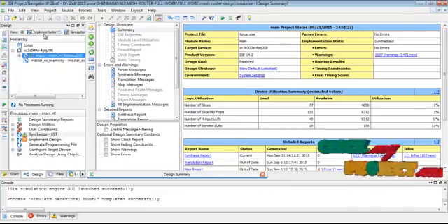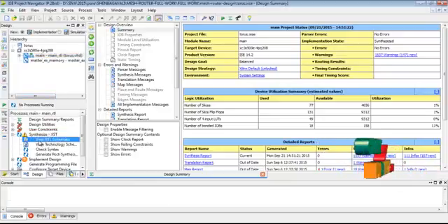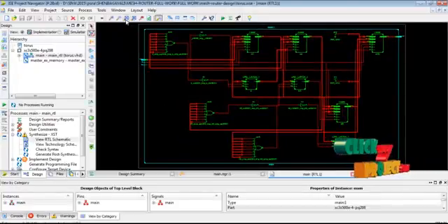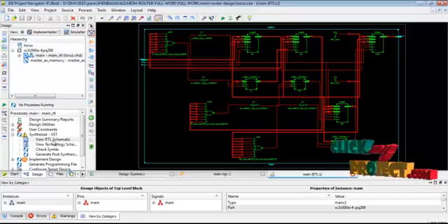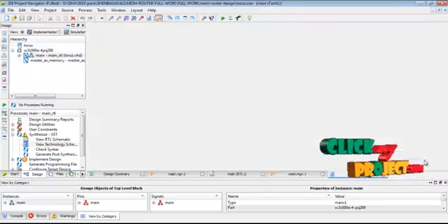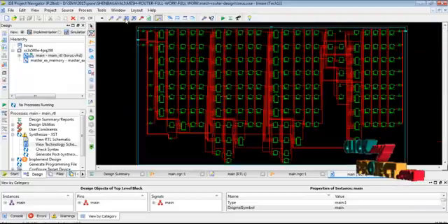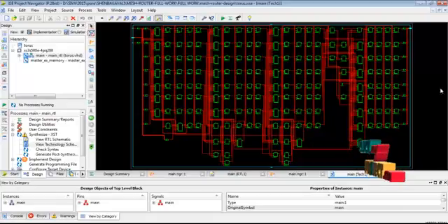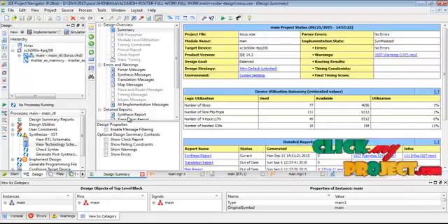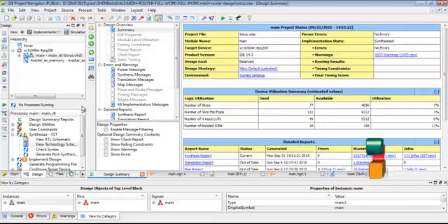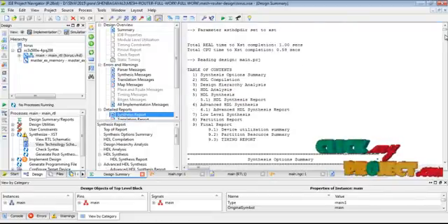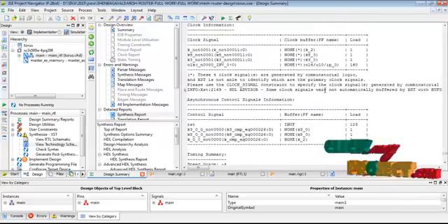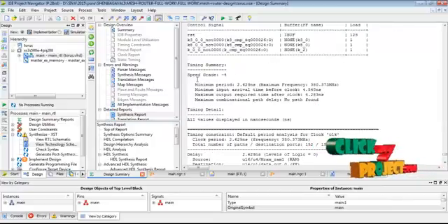And for the implementation design, we view the RTL schematic for our required architecture. This RTL diagram represents the logical blocks present in the overall NoC architecture design, and the technology diagram represents the input output pins, lookup tables, buffer connections, and flip-flop pairs present in the overall NoC architecture design. These are the lookup table structures for our final NoC architecture. These are the circuit complexity for our NoC based process, and we calculate the timing summary also. This is the synthesis report for the final data bits. These data bits represent the timing summary for the overall NoC architecture design.